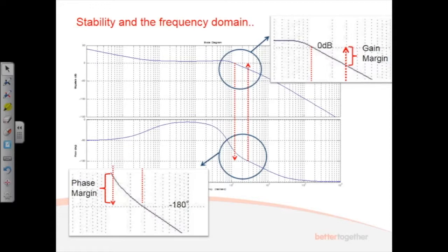Measuring the gain and phase margins from an open loop frequency response plot lets us predict what would happen if we close the loop. Okay, you get the idea? We're just looking for -1 really. We're measuring how close we are to -1.